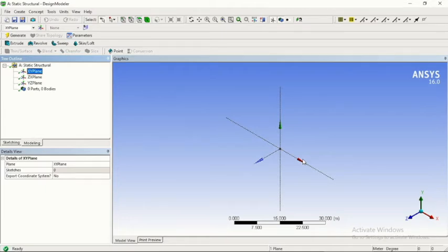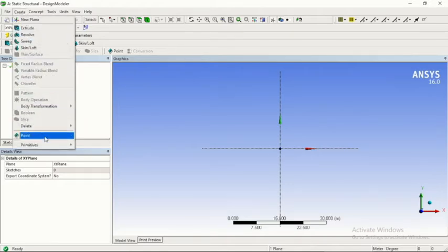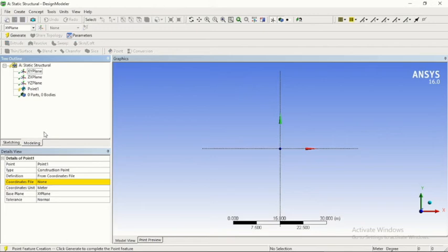So first we will create three nodes or three points, right? In the xy plane I will click on Look At Face or Plane. So I click this, then it will orient the drawing sheet according to the screen. Then I will use create point. Now if you look closely at the problem, example one, the lengths are basically 100 millimeters each, right?